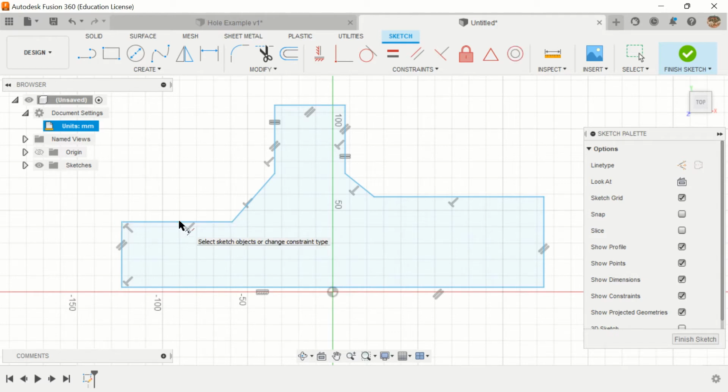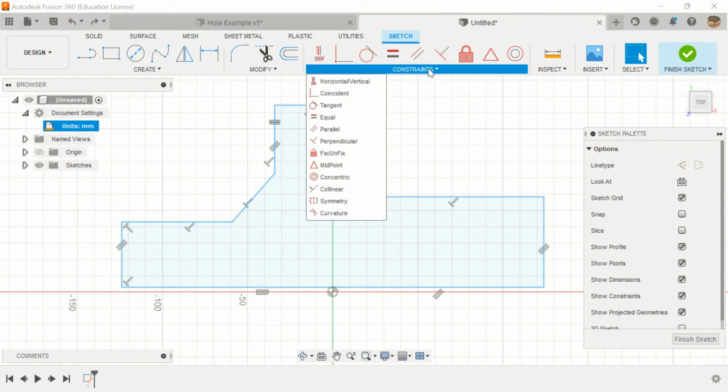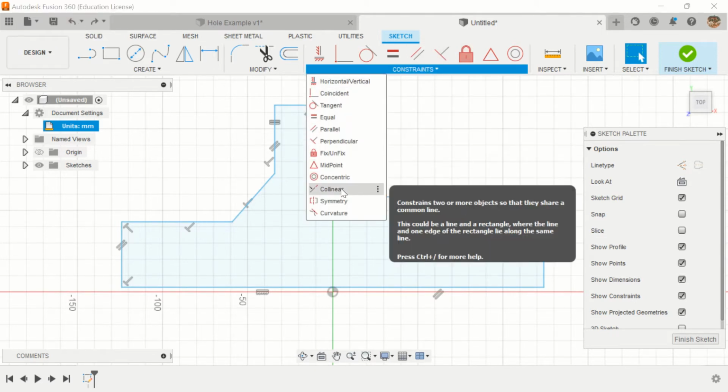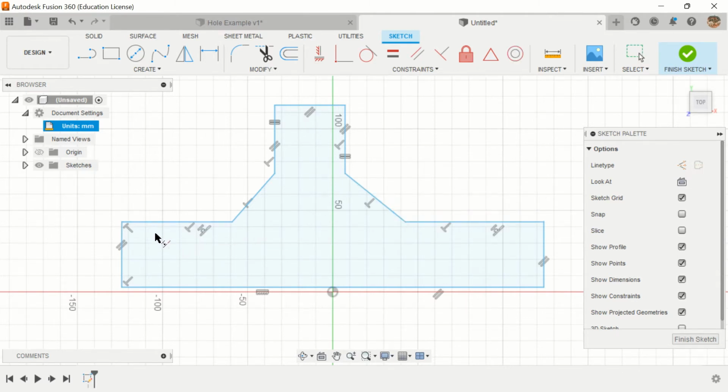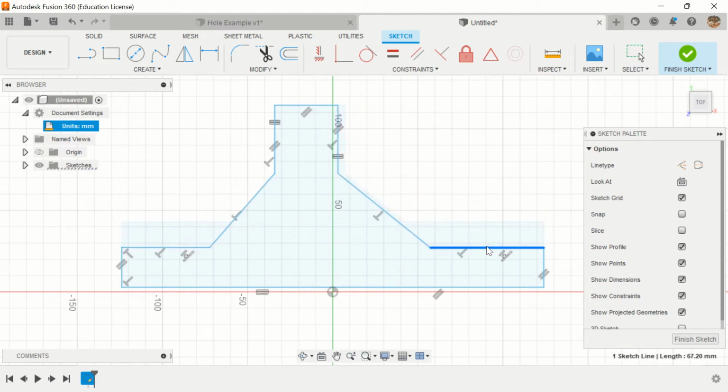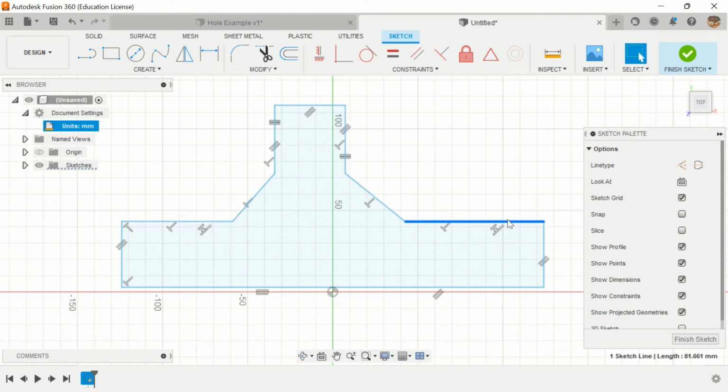So I'm going to go ahead and click line 3 and line 9. And you'll notice that it dropped line 9 down to line 3. Just for reference, if I had clicked line 9 first, oh no, in that case, line 3 must be locked in there. I'm going to mess with it. Now, if I click them and drag them, they move up and down together because they are now constrained to be on the same line.